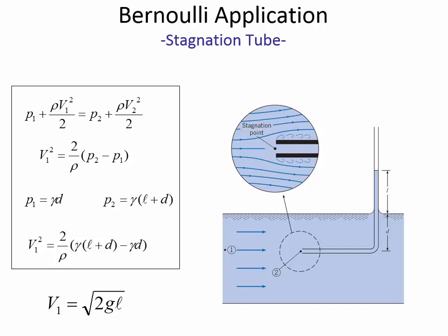Good question. So he's asking if the fluid isn't inviscid and it isn't incompressible, then what kind of error can you expect to see? In this case, I don't think that this is water, and so we're pretty close to the incompressibility assumption. So it won't be too bad for that. But what we're not close to when we're using water as our fluid is the inviscid condition. And so it depends on the shape of this device. So the inviscid assumption is saying the fluid has no viscosity and therefore there won't be any energy losses.